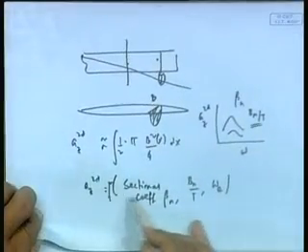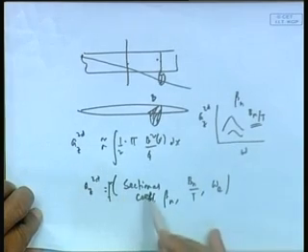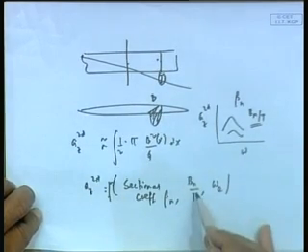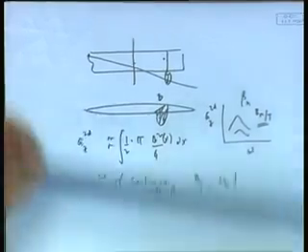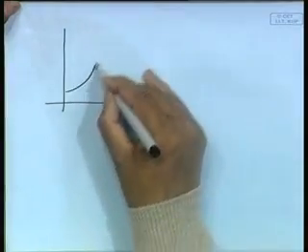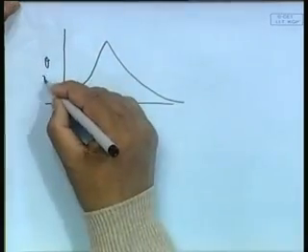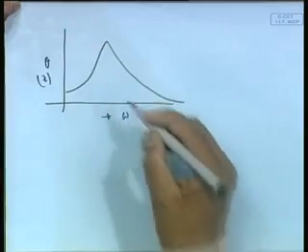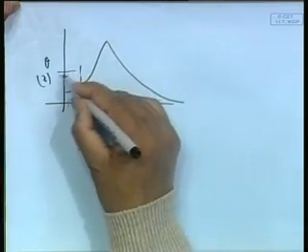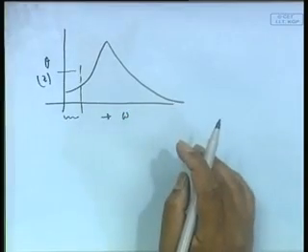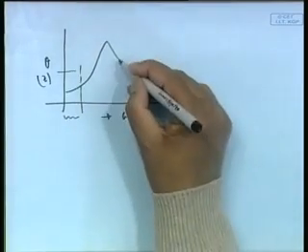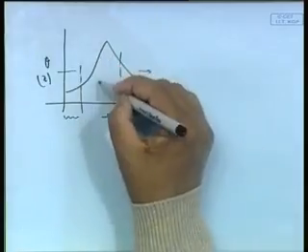The same thing will apply to damping. Exactly, damping is also available in this way, as a function of sectional coefficient, sectional width and frequency. Now there is another very crucial thing I want to tell you from the physical point of view of the behavior. Remember, this is my theta or motion or z and this is my omega. We said that this low frequency part is dominated by hydrostatic force. This is my high frequency part, the damping part.